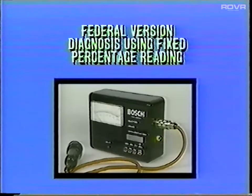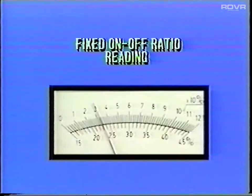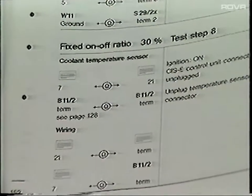Returning to 1988 Federal version engines, it should be mentioned that diagnosis remains unchanged from 1987 models. Problems are still diagnosed using the on-off ratio tester. You should be aware, though, that once a fault is detected by a fixed on-off ratio reading, Test C in the 1988 introduction manual can be performed to locate the exact cause.